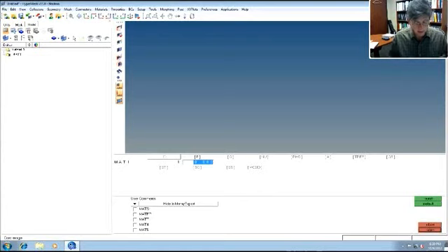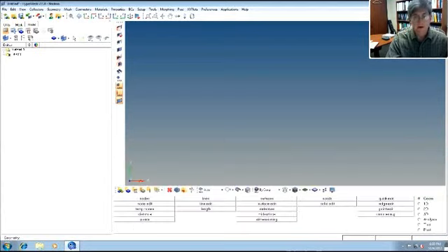You can put in Young's modulus. I forget what it is for birch, but let's just say it's, I don't know, 2 to the 6th. I think this is probably pretty high. Like 2 megapascal, mega PSI, and then also put in Poisson's ratio of like 0.3, and then show what it is. Okay? All right. So there you go. That's the material card.